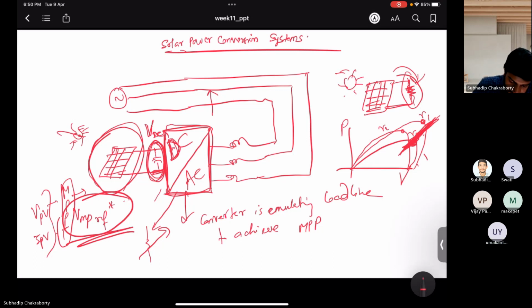Inductor. No, where will the power be drawn from? The grid, right? It will draw the power from the grid to maintain the DC link voltage using some PI loops, where the DC link voltage reference value will be coming from the MPP algorithm, such that your PV can push maximum power. Once you get that maximum power, you throw that into the grid.